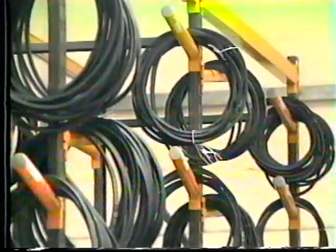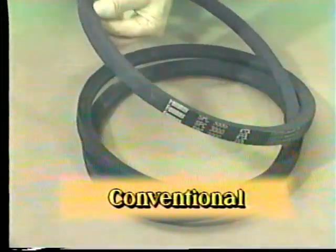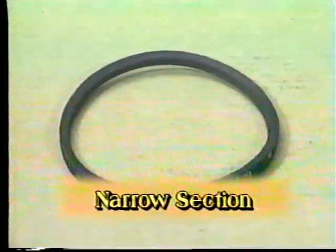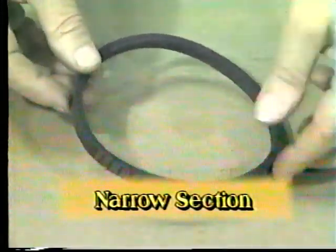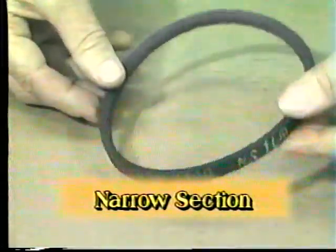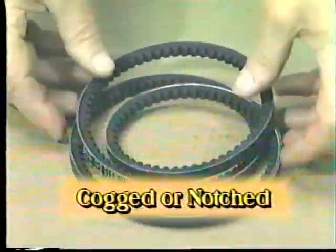Not all V-belts are exactly alike. The conventional or classical belt is still the most common, but the narrow section belts are also available. Even though they are smaller, their load-carrying capacity may be the same as a conventional belt. Both kinds of belts require their own special sheaves, and they are not interchangeable.